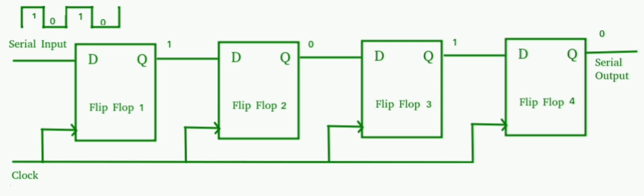Clear and preset are used in binary and non-binary ripple counters. Clear is used to reset the counter without clock. Preset is used to set the counter. When a decade counter counts from 0 to 9, then it is known as BCD counter.